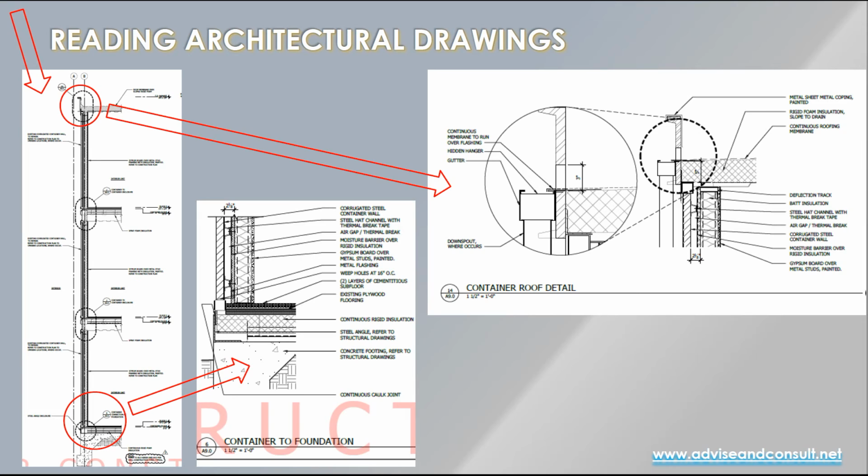So you're going to look at very fine detail of how flashing is attached, and again, you're not going to know what many of these elements are, but you'll know how to get to the detail of the parapet if you're talking to an architect on the phone or in a Zoom meeting, so that you can identify what drawing you're looking at, and you can say, oh, we need to look at the parapet detail that's on detail 14 on sheet A9.0, and the architect will go right to that drawing instead of working his or her way all the way from the first plan down to this specific detail. So that's something that can be very useful for you.